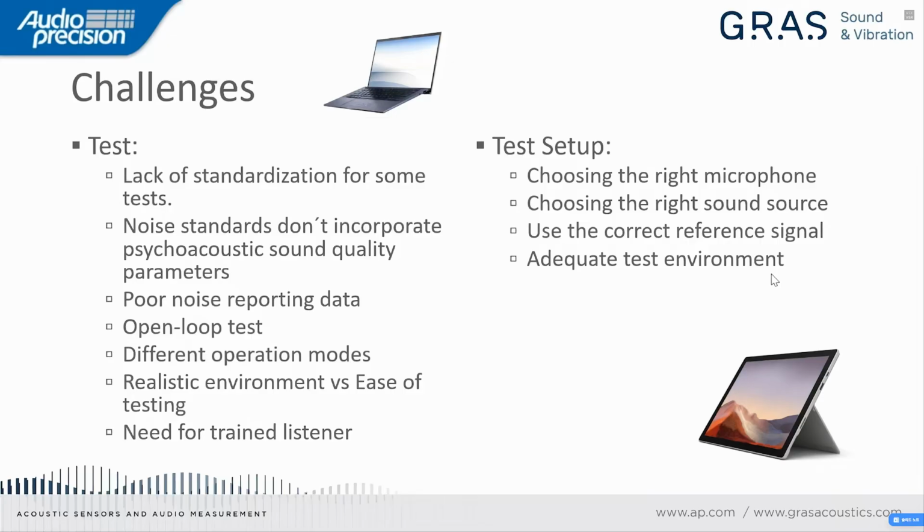And this is particularly important when we want to assess the annoyance that the noise generated by a laptop is creating to a human subject. It's important to remember that our ears are not FFT analyzers or sound level meters, and therefore adding psychoacoustic sound quality parameters to the noise testing can be something that is valuable.